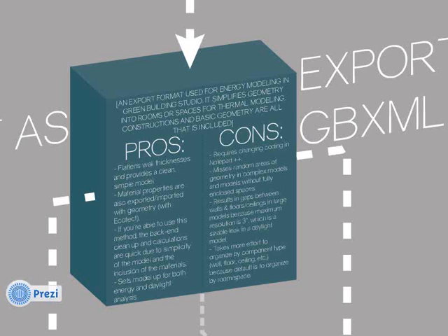Some of the cons, though, is there are a couple of conversion issues to get into Ecotect. For instance, if you try to just import a GBXML, you'll get an error, something about IFC conversion, so you have to save it as a different file type within Notepad++ or just Notepad. It's just one extra step, but not too big of a deal.